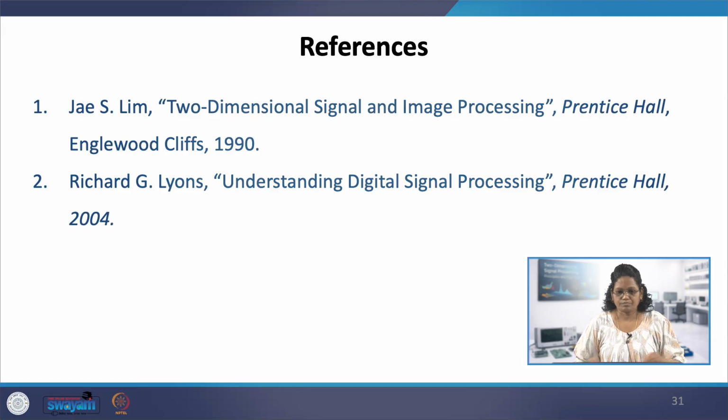So we had looked at two different methods of FIR filter design in this lecture. One is the frequency sampling filter, and the other one is the frequency transformation method. In frequency sampling filter design, in the 1D case we have to choose the k values for the resonators for which we need the band of frequencies. There is the passband and the stopband. So the k of the stopband should be neglected and the k of the passband should be added, or the resonator should be kept, to have the band of frequencies to be passed. This should be done in two directions, k1 and k2, as we have seen in the frequency sampling filter.